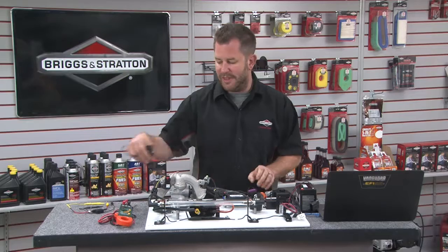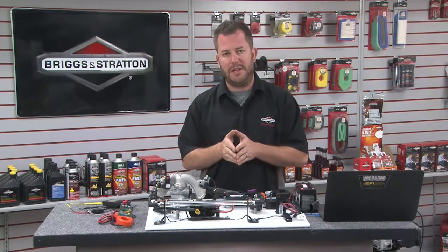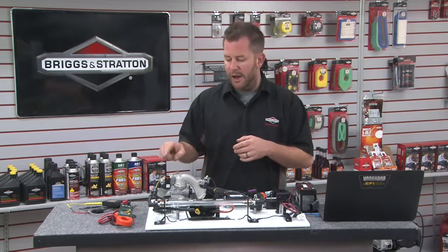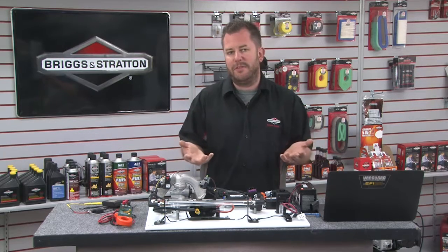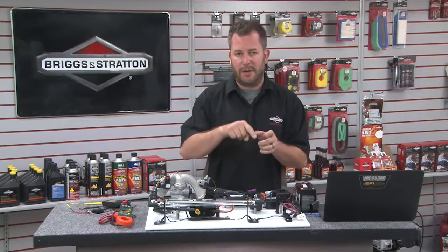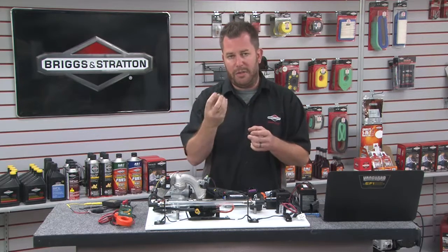So the 113 indicates a high voltage is seen here, meaning the fact that we're seeing 5 volts returned on our signal wire back for that temperature sensor. How it works really is there's 5 volts from the reference circuit that goes through the resistance of the thermistor.